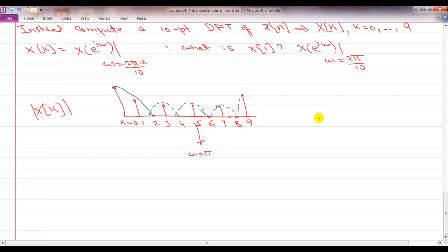So because of the periodicity of the DTFT, actually you can get to the conclusion that the DFT itself is a periodic sequence, even though we always calculate the DFT for k equal to 0, 1 up to N minus 1. If you ever were to input a k different than these values, your answer will actually be at k mod capital N. Okay, so what is this thing? This is defined as k mod N.